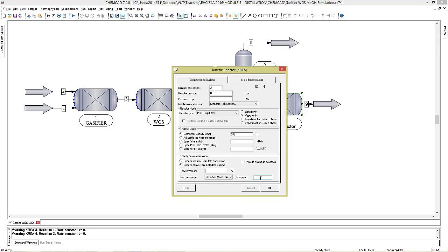A conversion is given as a fraction. So I will start with 0.05, which is 5% conversion. Methanol synthesis conversion per reactor is usually small. Conversion per pass is usually small because it gets limited by the equilibrium. In most cases from the literature, you will find that it is usually between 15 and 25% conversion. So it's very low, and you end up only converting 25% of the CO to methanol. I'm starting with just 5% to kickstart the calculations.